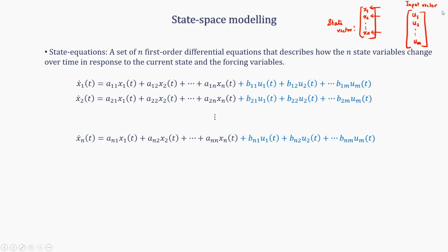Okay. So, you can see that corresponding to each state variable, now I am writing a differential equation. So, the left hand side is d/dt of x1, and these are a linear combination of the state variables plus a linear combination of all the inputs. Okay. Now, of course, the linear combinations will be different for different cases. So, for each of them I can write down these equations.